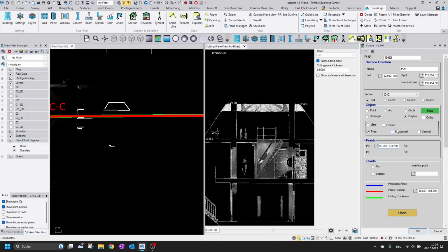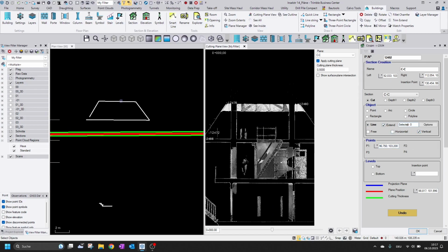And then, for example, if we want to create now horizontal or vertical lines or extending lines automatically, now we have two options. So for example, I could create now, let's say, new line, vertical, and now we can choose different elements. So for example, now I'm creating just this column. So a vertical one. So I pick here, and I pick here. And until now, we only had one, but we can say now, okay, for example, I'm creating an additional one, this one.